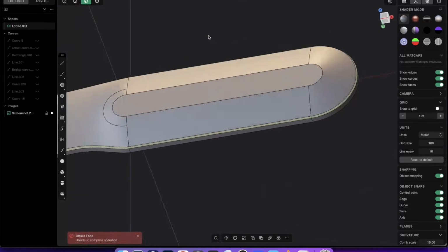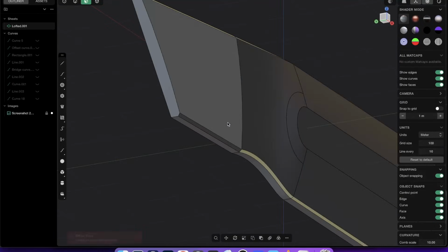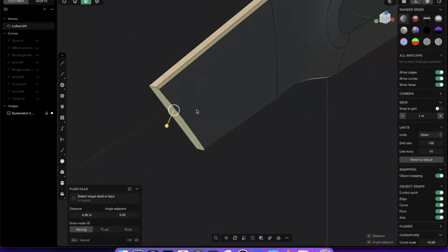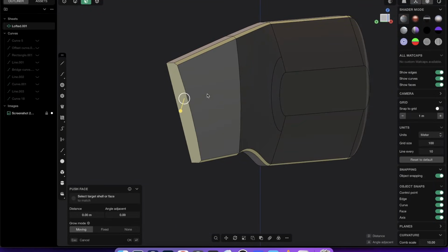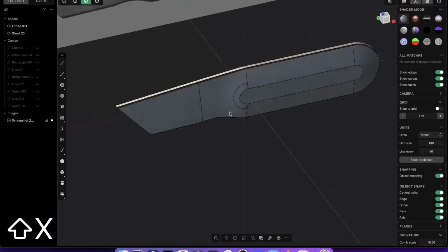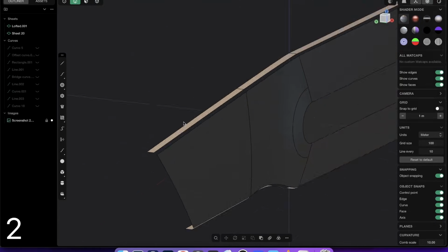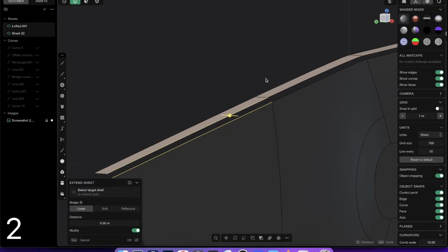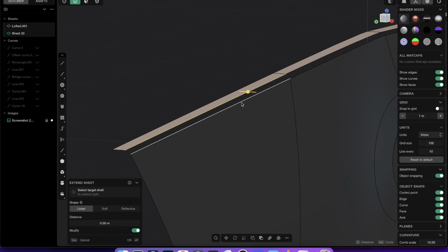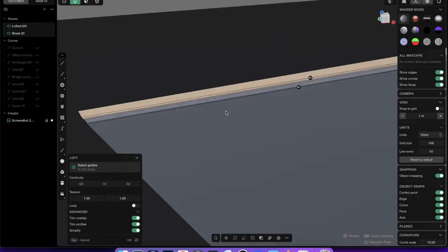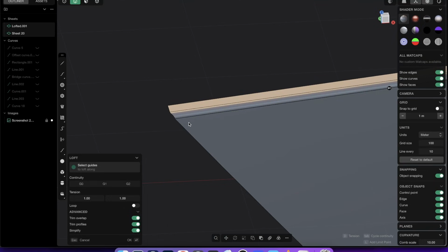So you just select this whole loop of chamfer surface and select this one piece at the bottom too, and this front face, because we will not need anything, and Shift X. And now we are left with that, right? Because now again, we can just press 2 and select one edge after another, and with shift click and just loft it. And we give it a fillet, but one more little thing.